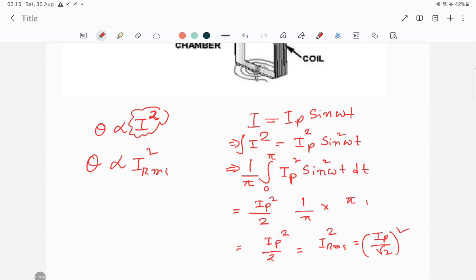In this root mean square formation, you square the 2 and take the root, so the RMS value will just give you the DC value itself. So you have to do the calibration while making the scale, so that the RMS value and the DC value can be shown on a single scale. That's why calibration is needed.